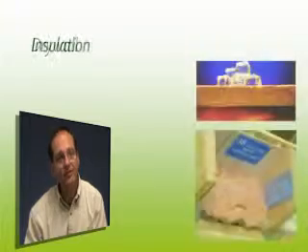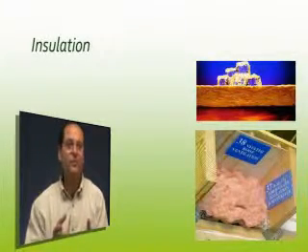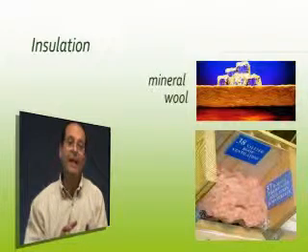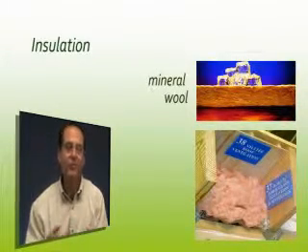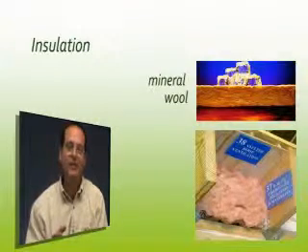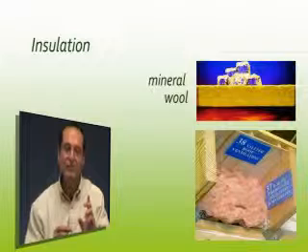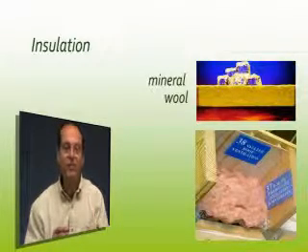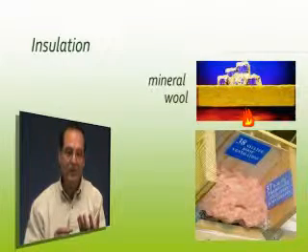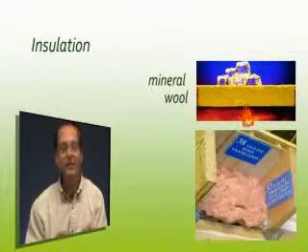Then there's insulation. Again, very specific. This particular system is mineral wool, and it's got to be 2.5 pounds a cubic foot. There's a couple different weights and varieties here, but as you can see in this picture, it's much more condensed. It's typically a thinner bat, maybe a few inches at the most. It's more dense, and it actually has the ability to prevent fire from coming up through the structure and from heating the elements above it and raising the heat.